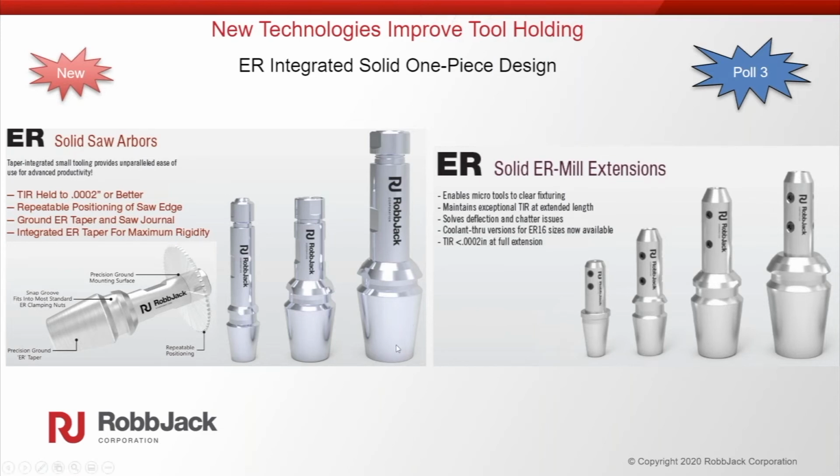We're holding TIR to 2/10,000ths of an inch with these types of extensions and arbors. And the huge advantage also is that you get repeatable positioning. So you could loosen up the saw, put another saw in, and it's in the exact same spot. So it really helps in medical applications, having this one-piece ER integrated design, and we have them in various ER sizes for both slitting saws and end mill extensions, which are kind of common in the medical industry.